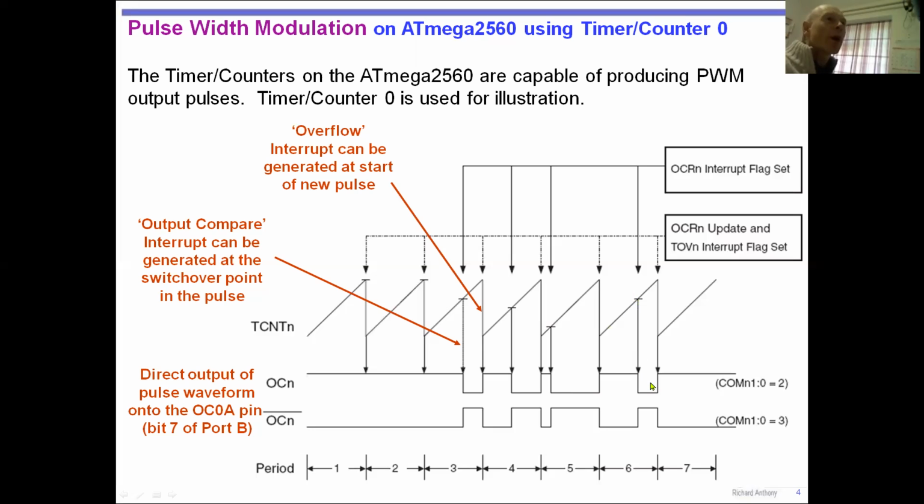That's the important part from this slide. You don't need to memorize every single part of this slide to understand the important point, right? We are changing the timer timing values in the registers, and by doing that, the pulse on the pin is changing. That's what you must understand. And the pulse on the pin is a square wave. It may not be a pure square wave, 50%. That bit there is approximating that, but the rest of it isn't. And we can change this.